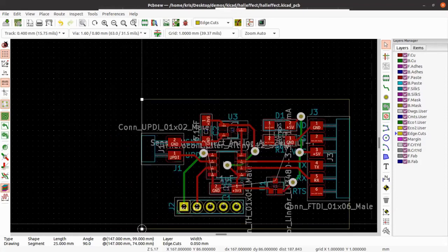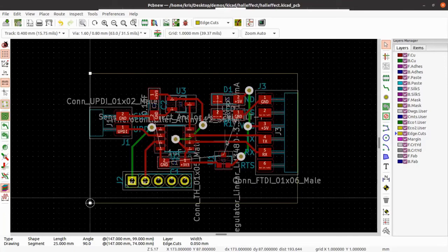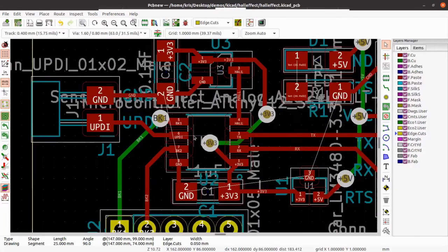And we can avoid doing some additional things in the design here that we did for mods. For example, we drew a margin around, and we also made an additional user drawings folder in order to make the SVG files so that they would be compatible with mods. So if you plan to work with CopperCAM, then that's not needed.